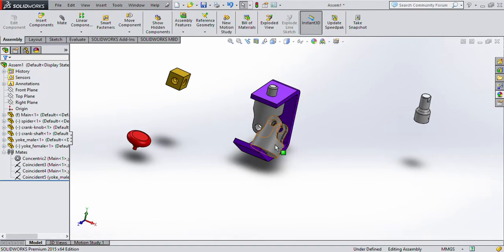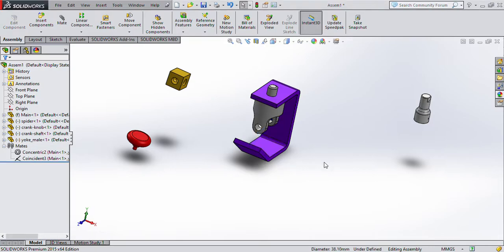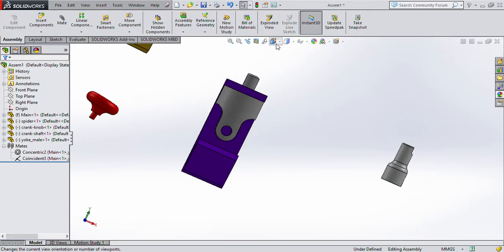the components. For example, now I'm going to select this one and delete. Okay, if you delete this component, definitely the coincidence 4 and 5 which belong to here will be recorded here. This is a way for finding how many mates are already applied to this component, and if it still has some problems with these mates, you can even delete your parts and recall your part again. But now I am going to continue with mate